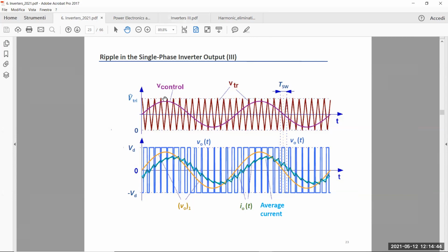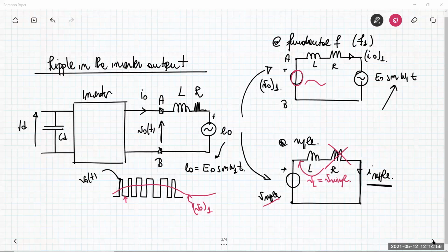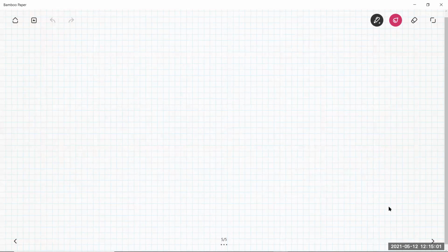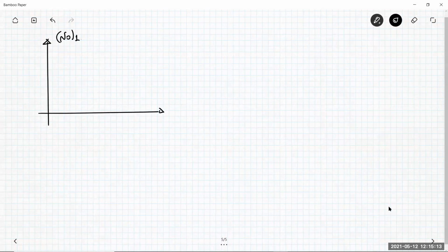Let me just move to another topic, okay? And in order to discuss this topic, I have to use the whiteboard. Up to now, we talked about the linear pulse width modulator. Basically, in this linear pulse width modulator, we learned that the amplitude of the fundamental component linearly increases for increasing amplitude modulation factor, ranging from 0 to 1.